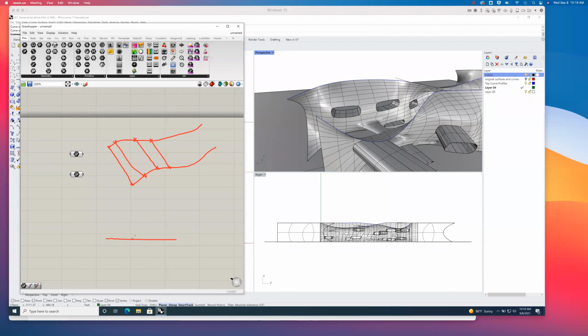Then for each of these lines, we're going to place a point along them, project upwards, get this point, use this point and this point, then draw some sort of arc-like interpolated curve or spline through them, right? Then we'll divide each of these, the top and the bottom, up the same number of times, and then we can start to create the trusses along it. So that's a set of conventional truss system along the length of this space, right? So that's the recipe, and that's the first workflow I'll go through here.